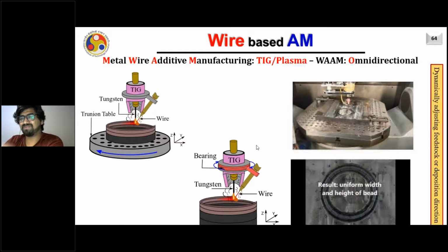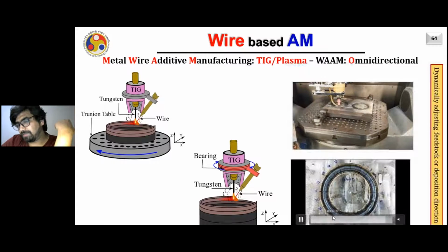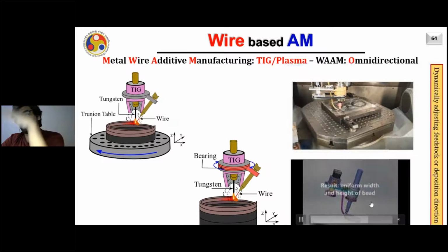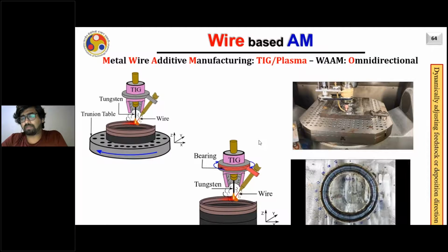No. Fine. It's okay. So, yeah, you can deposit the material by appropriately rotating the wire around the melt pool. So let me make a summary. If you're using TIG welding, you can't just retrofit it on a machine like a CNC machine or maybe on a robot and then directly use it.